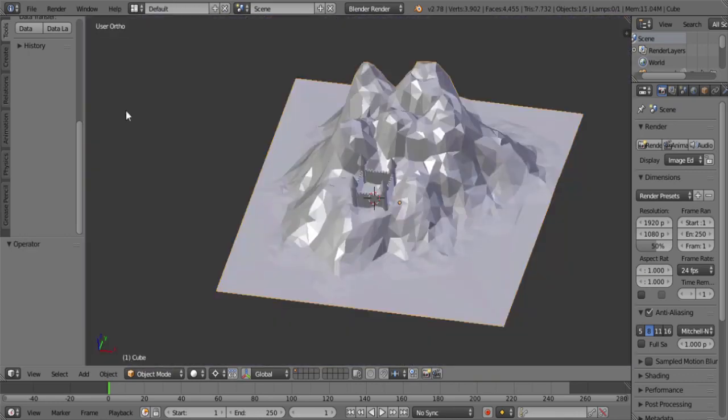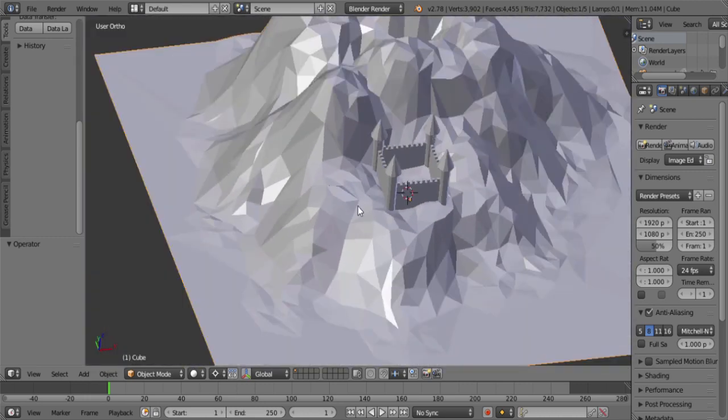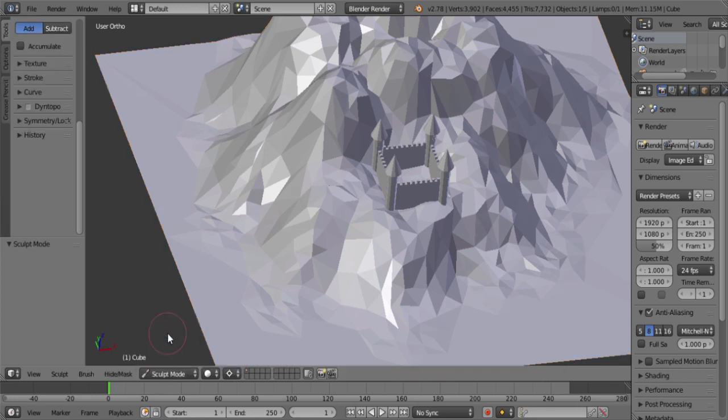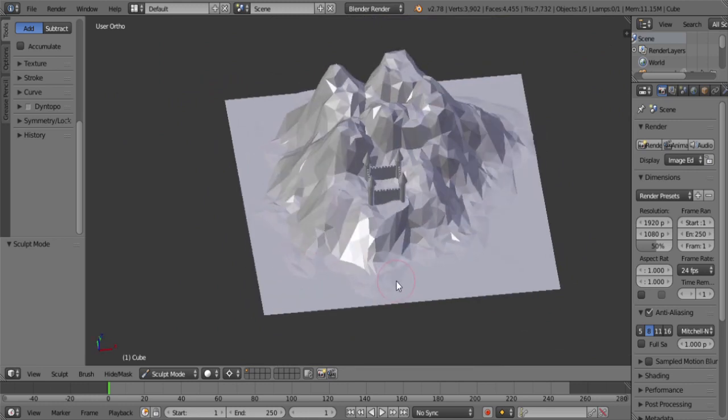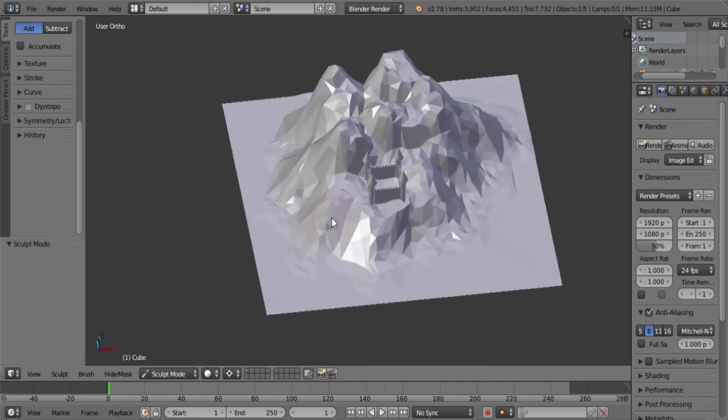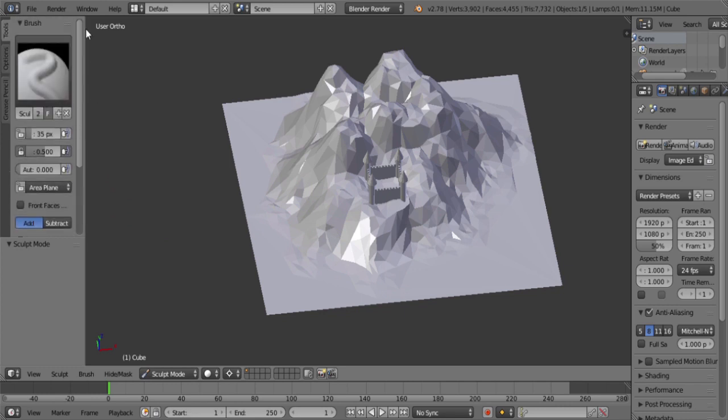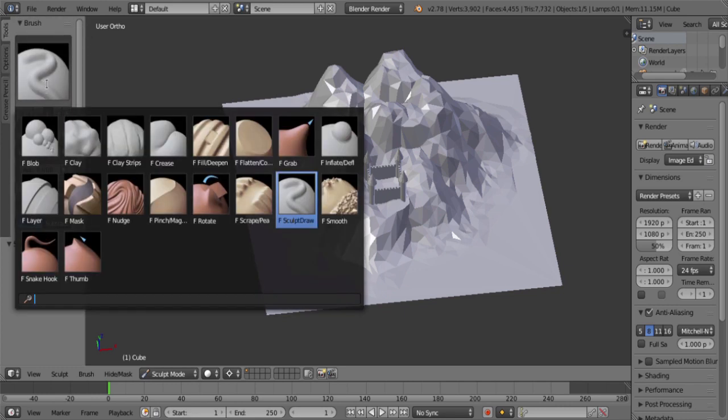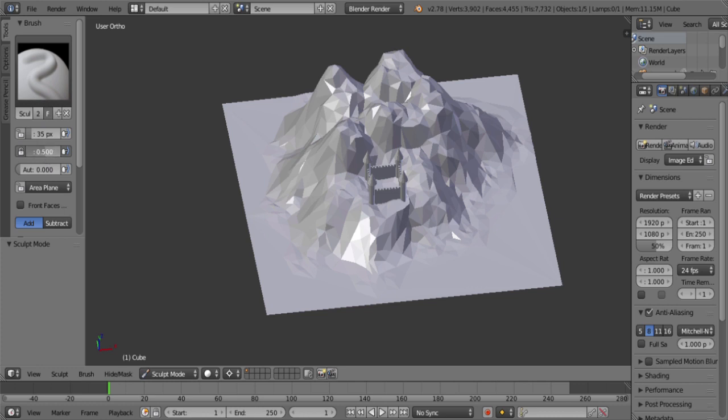that's that. So up to this point we just used extrusions and some design tools, but there are other methods to create shapes, and one of them is sculpting. I'm going to carve a path through this mountain, and I'm going to use sculpt mode. So instead of edit mode, we get sculpt mode. Now I've selected the mountain, and yes, sculpt draw seems a nice idea. I'm just going to increase its strength to 1 just to exaggerate a bit, and let's look at what happens.